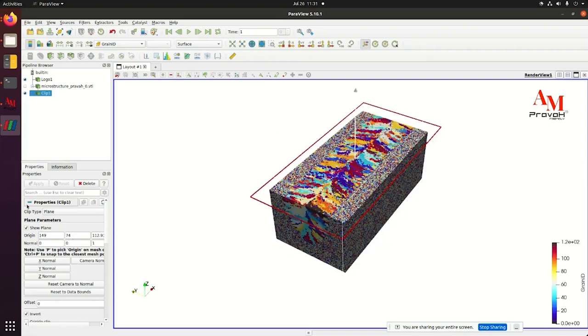With this view also you can see how the grain growth and the laser tracking can be seen. You can see how amazing it is that the grains and the laser tracks have merged with each other. Then this band is particularly having the equiaxed sort of grains, that is the merging of the columnar fronts.